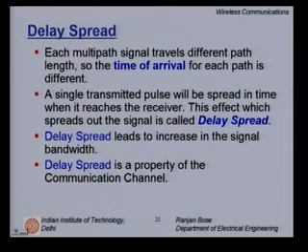But not everything is bad. See, the good part is that whatever signal energy I could have lost out is being thrown back at me through reflections. So, if I have a special receiver which can grab the energies coming after certain delays and put them together coherently, because remember, all the signals which I get are of random phases, I just cannot combine them.